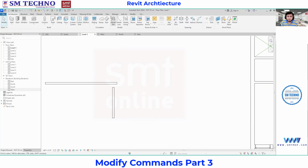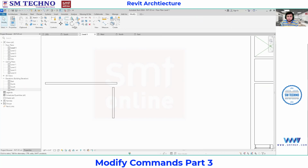So when you are going with the trim option, go to Modify. In the Modify panel, you can see we have got three things. One is trim or extend to corner. Next we have trim or extend single element. The third one is trim or extend multiple elements. This is the first option. That means you want these two walls to make a 90 degree bend, so you select this one and this one. What is happening? It will remove the unwanted part and extend till the end point, which gives you a 90 degree angle. This is called trim or extend.